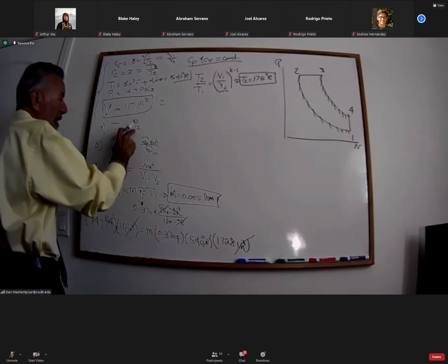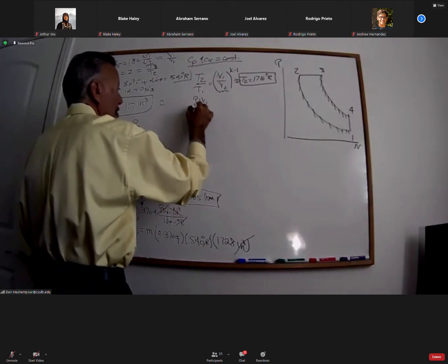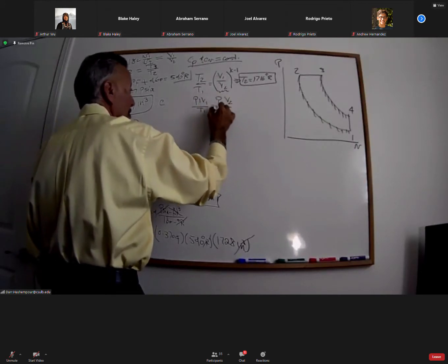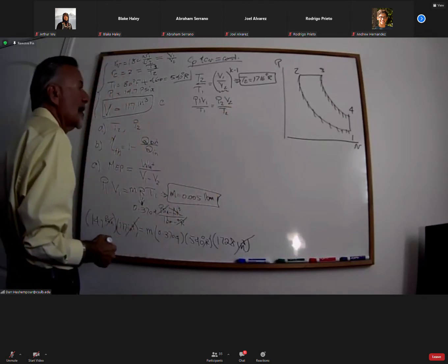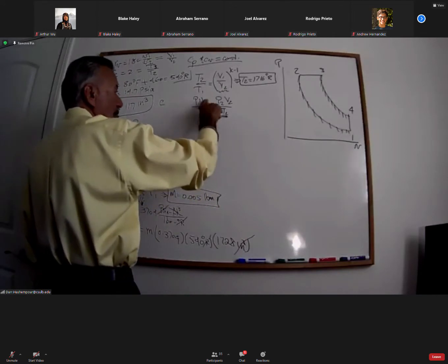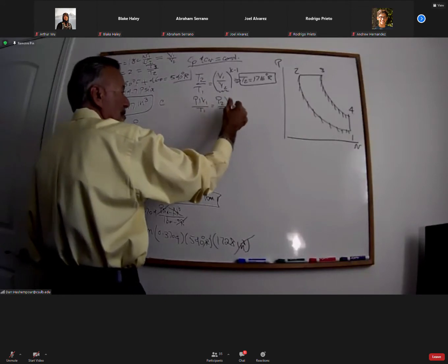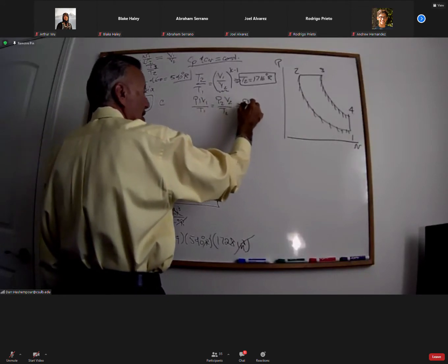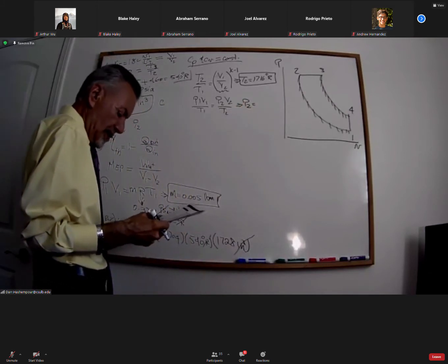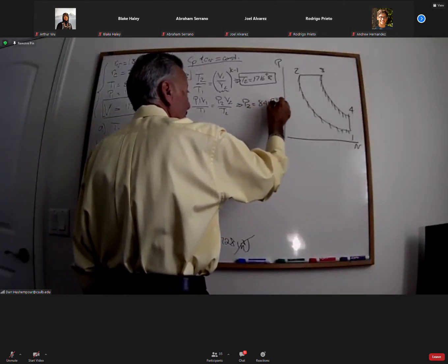Then they ask, find the pressure. Well, I know that P1 V1 over T1 is equal to P2 V2 over T2. So I have T2, I have T1, I have V1 over V2, and I have P1. The only unknown is my P2. So from this relationship, I can find the value of P2 to be 841 PSIA.